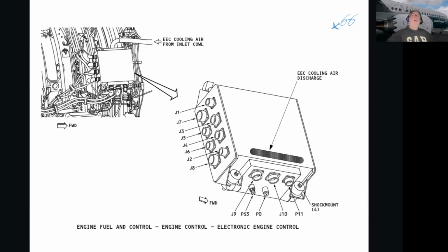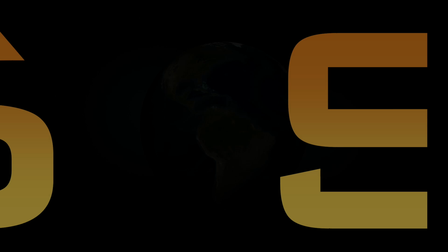It's responsible for the high pressure turbine active clearance control and the low pressure turbine active clearance control. It also gives indications in the cockpit. It's an expensive bit of kit. As we know, the FADEC is the brain of the engine. Very reliable though, with two identical channels, so it invariably doesn't go wrong.